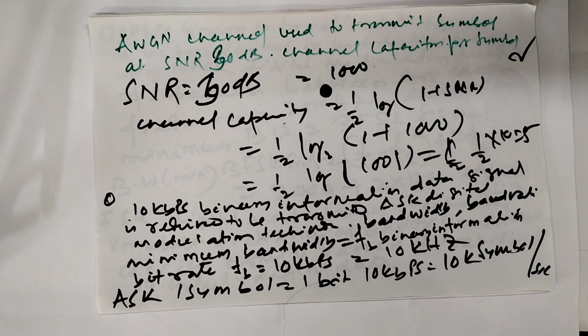In frequency shift keying, the frequency of the output signal will be either high or low depending upon the input data applied. In phase shift keying, the phase of the output signal gets shifted depending upon the input. There are mainly two types: binary phase shift keying and quadrature phase shift keying, according to the number of phase shifts. The other one is differential phase shift keying.